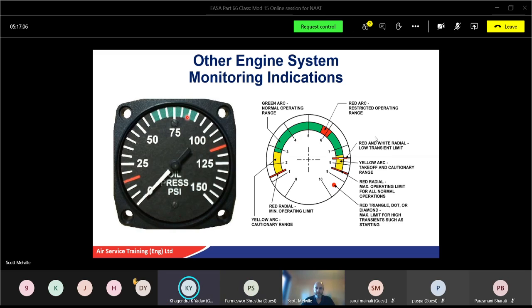Not compressor inlet. Pressure outlet. Yeah. So compressor outlet's the cold stream, and then your core engine, which would be your standard engine, would be your hot stream, exhaust pressure. So the fan pressure, your cold stream, and your hot stream, mix that together, and then compare that again to your compressor inlet. Good.